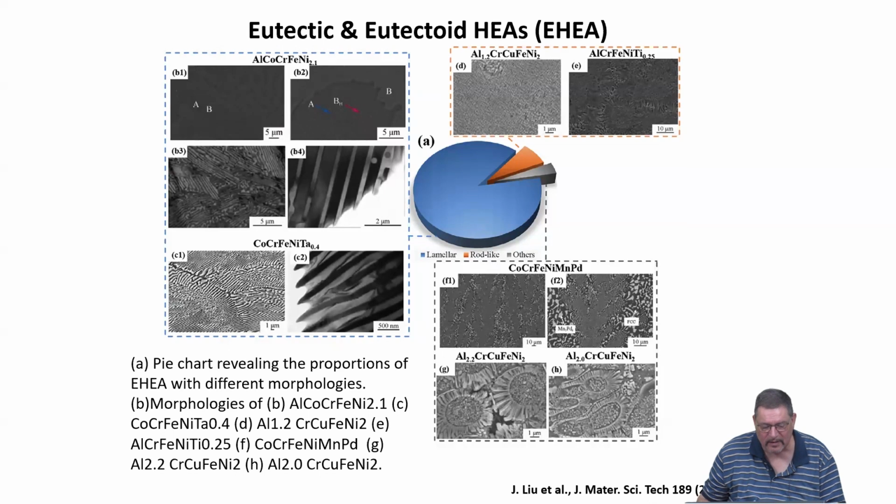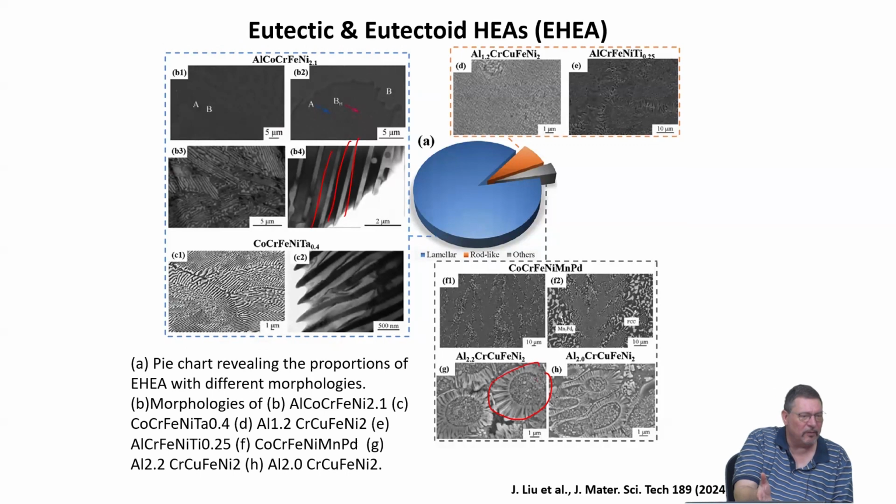And you can nicely see some of the eutectic features which you get are really very, very much as textbook-like, right? So you wouldn't see from the microstructure that these are high entropy alloys, right? So it means all of your knowledge which you have gained from the AB systems, binary systems, you can directly transfer to high entropy systems, even to complex systems like eutectic high entropy alloys.